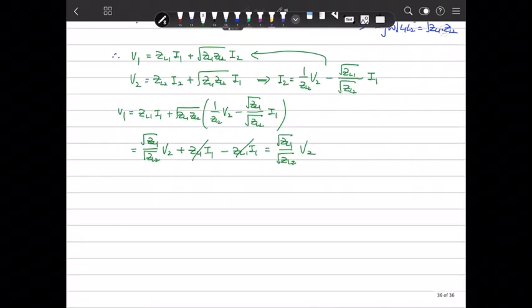When you make up the coupling model, we assume that L1 is proportional to C1 N1 squared, and L2 is proportional to C2 N2 squared. When your coupling coefficient K is 1, that means C1 and C2 are the same, because all the flux is coupled in the same coils, I mean the primary coil and secondary coil.